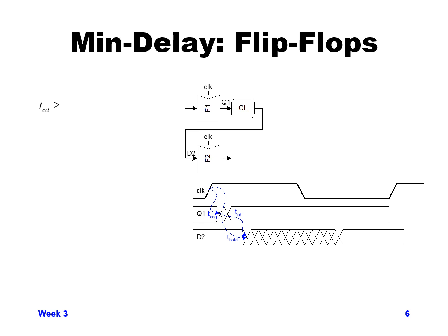This is related to just a single clock edge, and how much time it takes to get through the combinational logic, and can it go through too fast. This has nothing to do with the frequency of the clock. It just has to do with, do you allow data to go through your sequential element too fast and get to the next sequential element before it's supposed to switch.